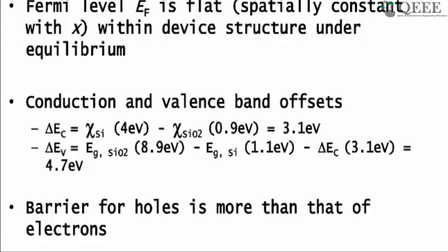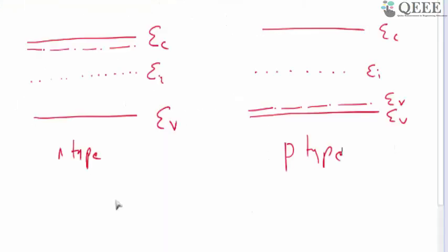Somewhere above the material there is something known as the vacuum level. If any electron is present at the vacuum level, it is free to move. If you want to eject an electron from this n-type material, this is your EF, and you need to give this amount of energy, between E vacuum and EF.